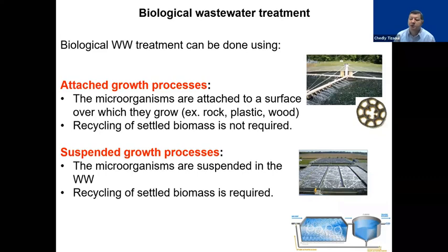So if you think about a particle that has a diameter d, the specific surface area for that particle, as you may know, is 6 divided by the diameter. So if your diameter goes down, the surface area of contact goes up. Okay. So in our case, you have those particles, you suspend them in the wastewater, and they will give you the treatment of the wastewater.